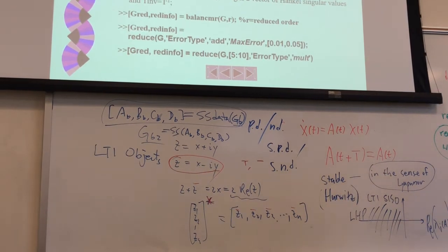After we did this balanced realization, we can see that here. Okay? So suppose we do that cancellation. It's called truncation. Those less controllable, less observable states, we don't need them, so just throw them away. That's the way to do model reduction, and model reduction has very good physical insight about what you really throw away and how much you lose.